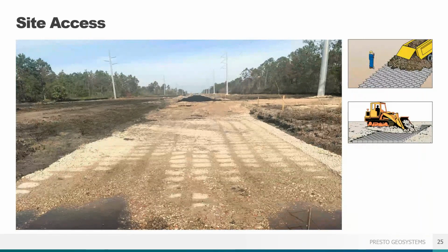Once the panels are filled in, both wheeled and tracked equipment can drive over these systems easily, even when the infill material is sand or other low-quality stone. Again, we see how the GeoWeb panels act as their own access road. You just keep filling up the cells in front of you. No need for additional temporary roadways for the construction. This is a great time and resource saver.